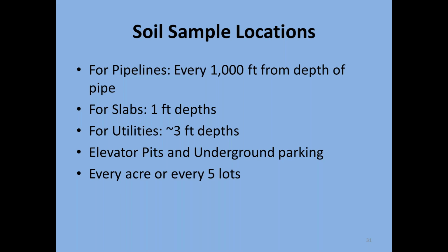You may actually have a very corrosive strata deep down, but you won't be aware of it because you mixed it with maybe very non-corrosive soil closer to finished grade, and it dilutes. So you may have a surprise pipe leak, or utility problems. So that's something to keep in mind.